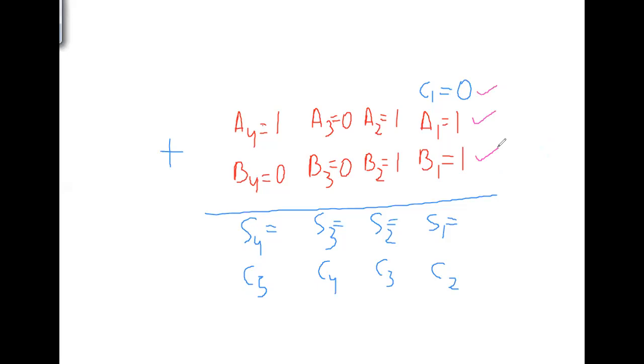So first of all, by using a full adder, just add these bits. 0 plus 1 plus 1 is equal to 1 plus 1, already you know, is a 0 with carry 1. So S1 will be 0, and what about the carry bit? It should be 1, right? And that carry bit is written as C2. Why? Because it is the carry for the second bit.